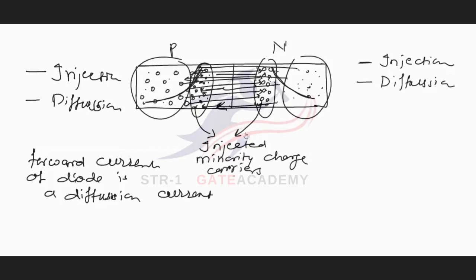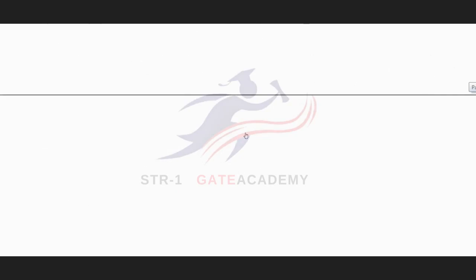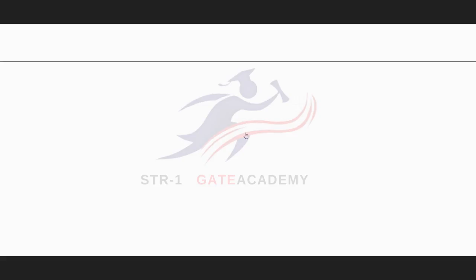So in a forward biased PN junction, the current will be a diffusion current. Majority charge carriers will be first injected and then these charge carriers will diffuse from higher concentration to lower concentration. In this way, a PN junction diode in forward bias will conduct. Now we will draw VI characteristics of a forward bias PN junction.